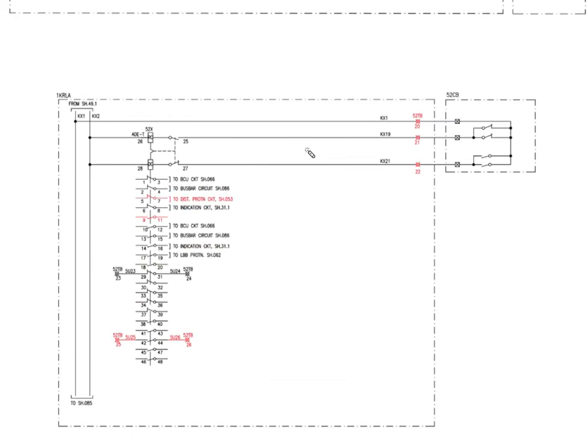No, this is the closing circuit. This is the CB status. So the positive we give is KX1, and then it is given to 52 TB 20 in the relay panel. Okay, this is positive 52 TB20, and when the circuit breaker is in the off position, the positive will come to 52 TB21.